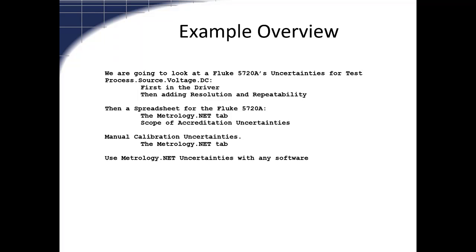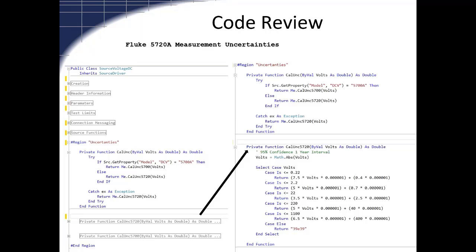Now, most of the manufacturers will tell you that their Type B specification is going to include the cal traceability when they specify the instrument, but they don't document that inside of their manuals, so some auditors won't accept that that's in there, and they'll require you to add in your cal traceability on top of your measurement uncertainty. So that's one of the reasons why some labs will have to come in, add in that spreadsheet so they've got an alternate uncertainty calculator, especially for their higher end calibrations.